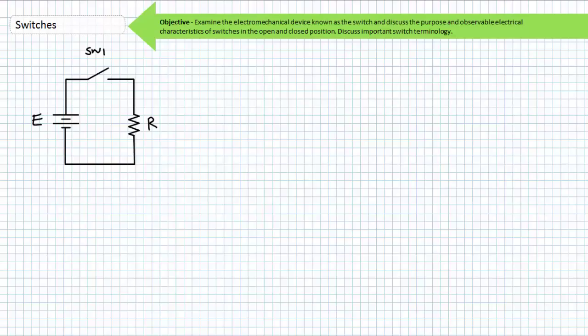of an overkill. The point is, the mechanical aspect of making or breaking a conductive path is a brief moment in time when the non-ideal nature of switches and real-world physics become vitally important considerations. The business end of a switch are the contacts. These are electrically conductive devices that, when touching, allow current to flow, and when separated, do not. They're physical parts, and when subjected to abuse or long use, can wear out and fail.